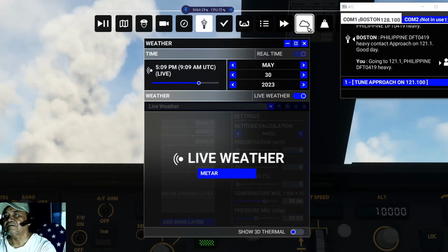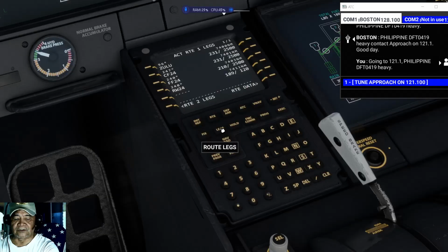Alright, so let's prepare our landing: ILS 24 on Zulu. Okay, there you are. The approach is on 154 knots at 30 degrees flaps. Navigational radio for ILS 24 is 109.9, it's already confirmed, and we are going to be on the same position.